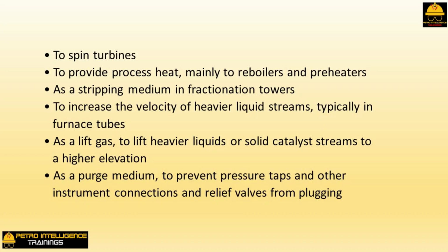To spin turbines. To provide process heat, mainly to reboilers and preheaters. As a stripping medium in fractionation towers. To increase the velocity of heavier liquid streams, typically in furnace tubes. As a lift gas, to lift heavier liquids or solid catalyst streams to a higher elevation. As a purge medium, to prevent pressure taps and other instrument connections and relief valves from plugging.